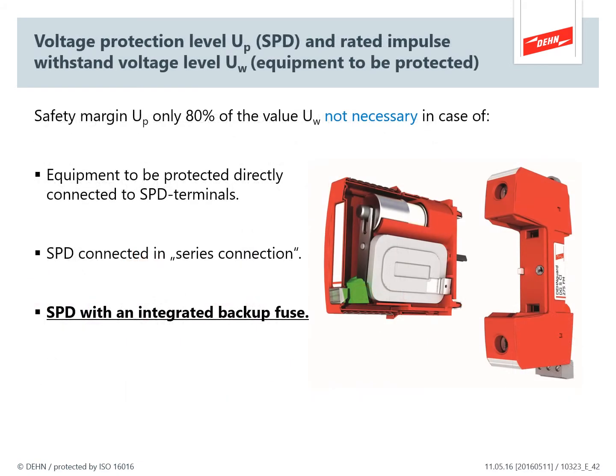The other way that we can reduce the voltage protection level, or the way which is certainly applicable in panel builder design, is the use of SPDs which have built-in overcurrent protection. In other words, an integrated backup fuse.